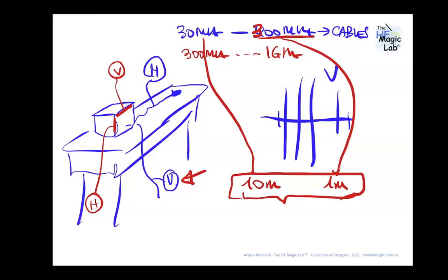Why does your circuit not have an earth connection, and why capacitors to reduce the EMI? Well, earth connection is a question related with safety. If the voltage you are working with is not unsafe, and I was working with 20 volts, there is no need for earth connection for user protection against electrocution. So I have no Y capacitors in these applications. The Y capacitors are used normally for conducted emissions up to 30 megahertz.